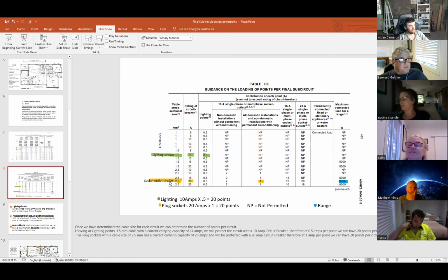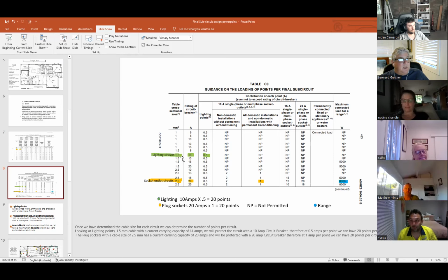You have to use that size cable as a minimum. Oh, of course. Okay. With lighting, there's not much difference between 1 millimeter squared and 1.5 millimeter squared. Realistically, for what it's worth, given the amount of problems you can have with 1 mil, it's better to have the 1.5 these days.